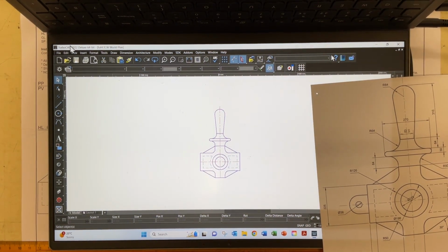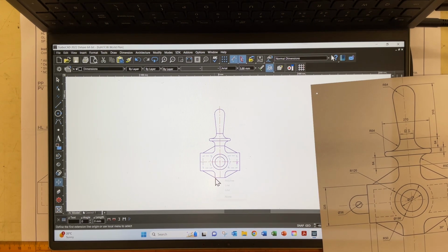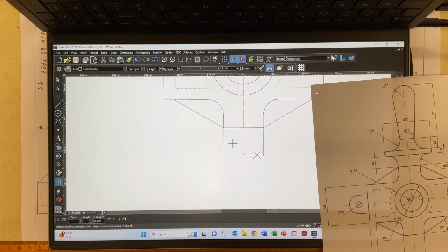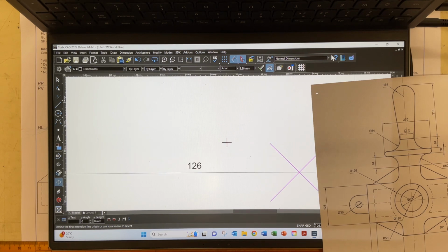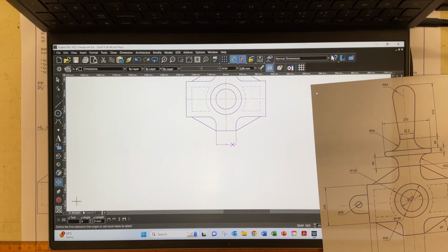All right, if I had to start drawing dimensions straight onto this, okay, click that. Let's just do line, click that, line. Right. If you look over here, the dimension is so tiny that you can't see it. It's just too small. It's not going to come out on layer space. So I need to adjust the size of my writing on this thing and the size of my arrows and everything so that I can actually read it. I'm just going to go Control Z to get rid of that.